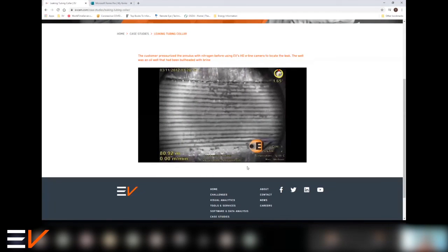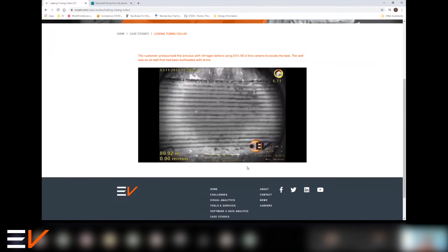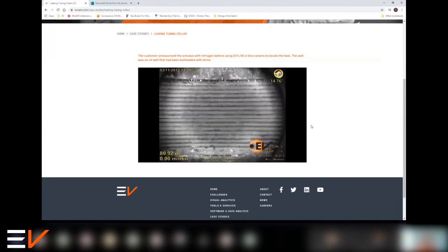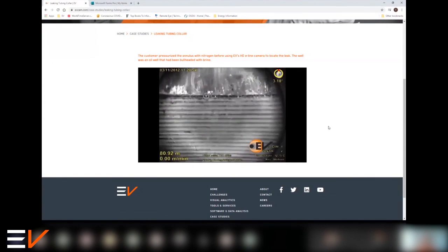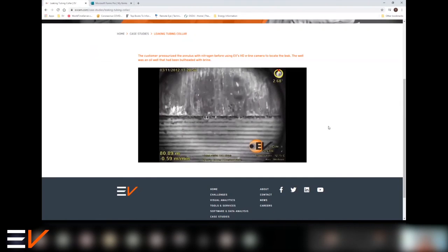It's tiny. You might be able to pick that up with an acoustic leak detection tool, but certainly seeing it and understanding the cause of the failure, the video is fantastic for that. And when we switch to the side view image, you can actually see the bubbles leaking through the connection threads here. So just a little note to say the way we're streaming this with Microsoft Teams, these videos probably aren't being shown at their greatest frame rate and resolution.